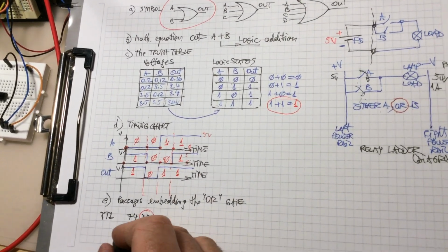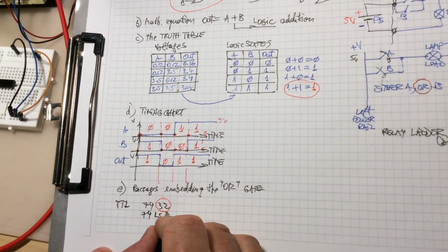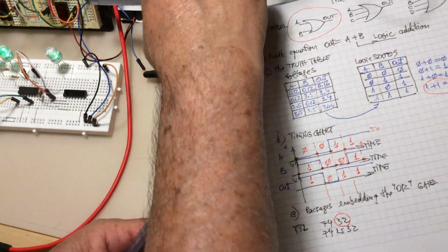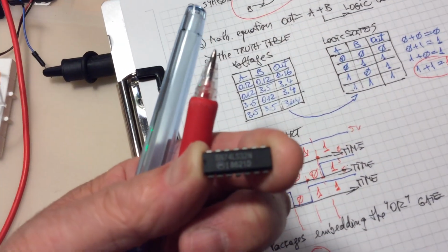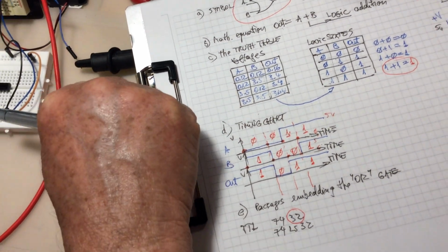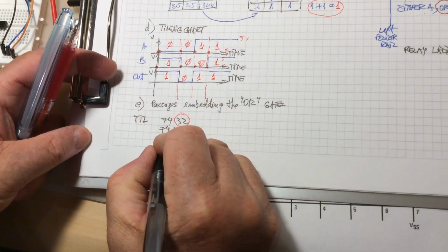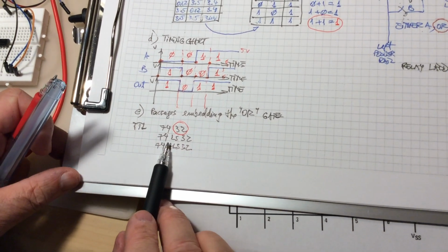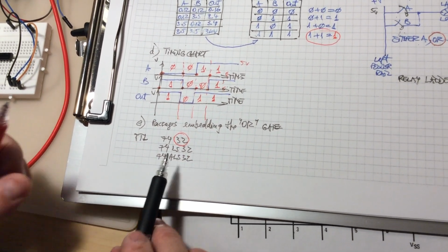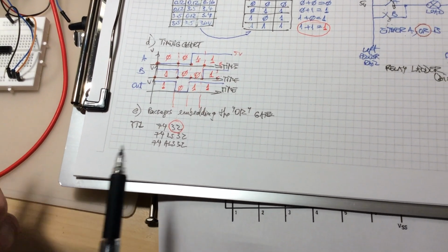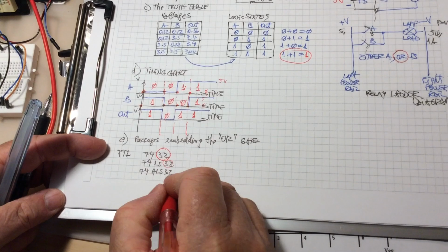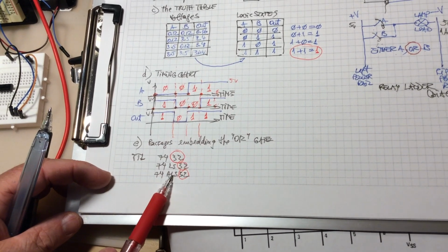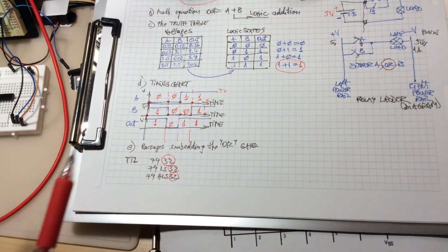You may also have 74LS32. Like our package here, this one here, is 74LS32. And you can also have 74ALS32. Remember, LS stands for low power Schottky, or high speed. ALS, advanced LS. So here I'm going to circle again, and you can see the number remains the same because it doesn't matter the technology, original TTL or LS or ALS, the diagram is still the same inside.